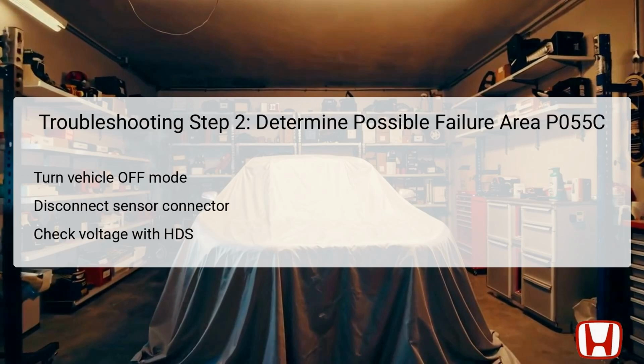In this step, you will turn the vehicle to the off mode and then disconnect the rocker arm oil pressure sensor 3P connector. Next, you will turn the vehicle to the on mode again and proceed to use the HDS to check the sensor voltage. The expected value should be the same as before.